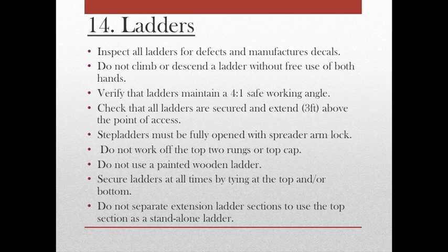Ladders. Inspect all ladders for defects and manufacturer decals prior to use. If unsafe, do not use and report to the supervisor. Do not climb or descend the ladder without free use of both hands. Always use the rope and or rope bucket to raise and lower tools and materials. Verify that ladders maintain a 4:1 ratio, safe working angle. Check that all ladders are secured and extend 3 feet above the point of access.